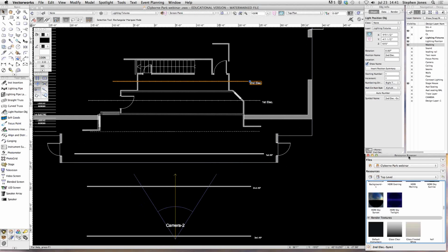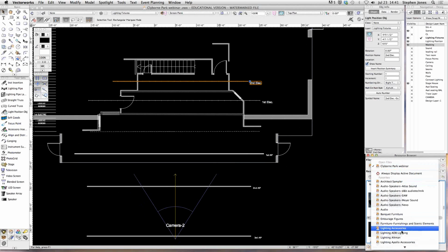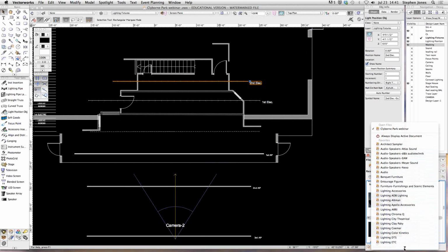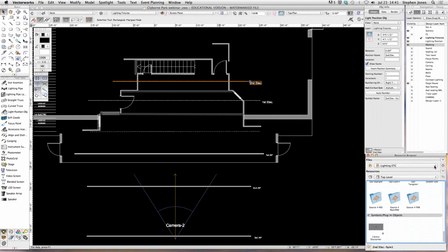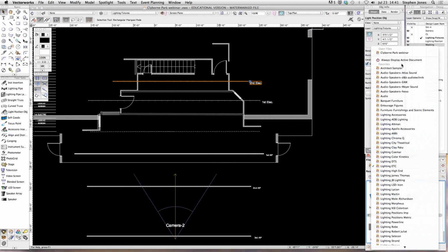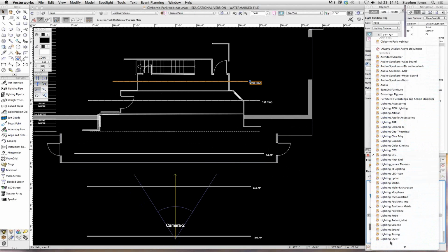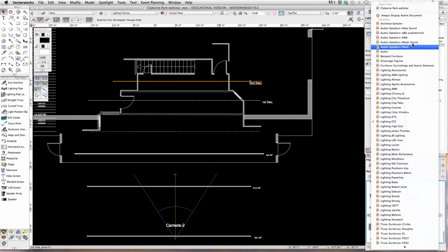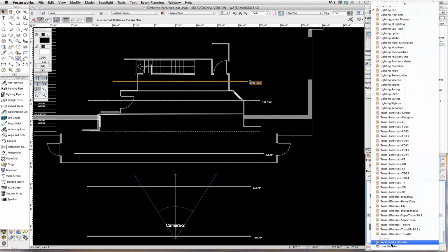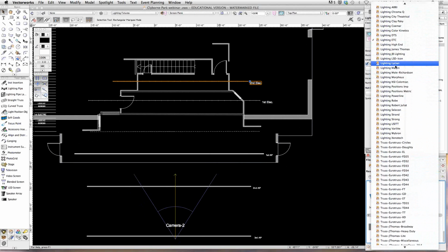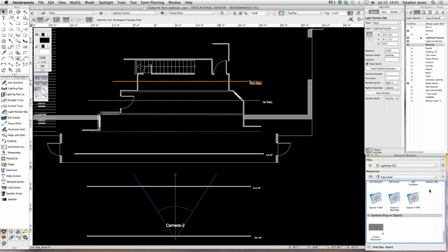When it comes time for hanging fixtures, again, I love Vectorworks for the fact that it does all of the work for you. Under the resource browser, you can come in, we'll use the lighting etc, okay, so under the files you can go lighting etc, and I should stop at this point and say if you don't have these under your favorites, all of these presets here, as a theatrical lighting designer, my favorite presets are all lighting related, you can still find these options under Vectorworks libraries, okay? I just happen to take the Vectorworks libraries and put them into my favorites.